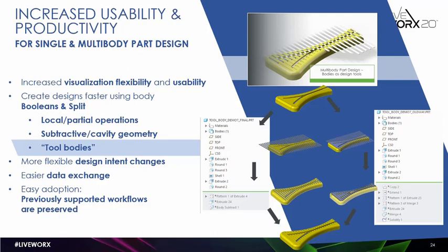In those situations, working with surfaces typically requires the creation of more features, and it requires also to switch to a different set of surface and quilt based tools or commands like trim or merge. It can also come with some limitations. For example, you can't drill a hole into a surface quilt. So for those cases, using solid bodies in combination with Boolean and split operations requires less features, less expert knowledge, less switching between solid and surface modeling tools, and allows for reduced modeling time with more intuitive and easier design solutions. This also makes the ramp up easier for new Creo users learning the tool.